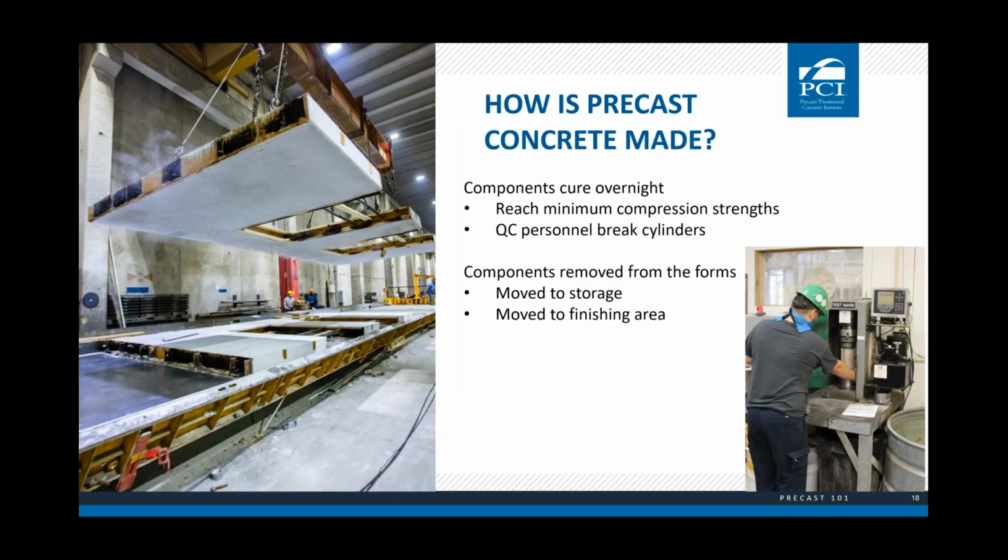Now, depending on the product being produced and the mix design required for that particular product, the concrete is designed to cure in 8 to 12 hours. Once it has reached the minimum compressive strength, the units can be removed from the forms and moved to the finishing storage area.